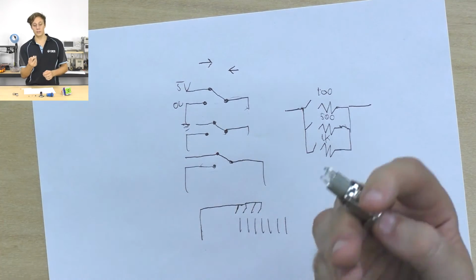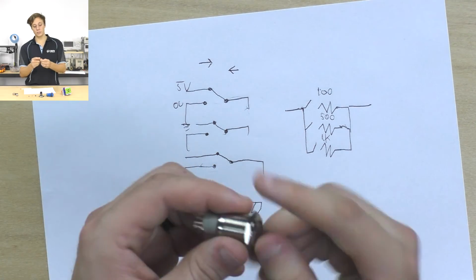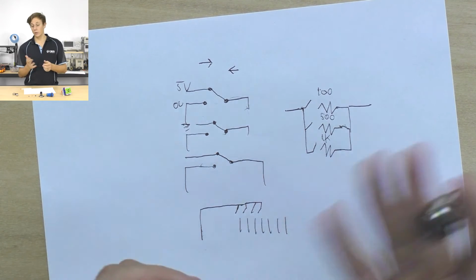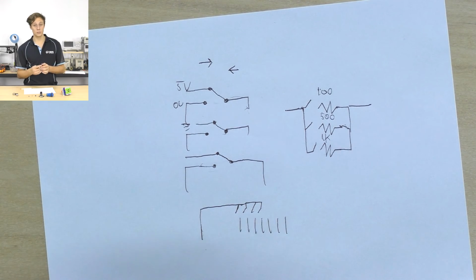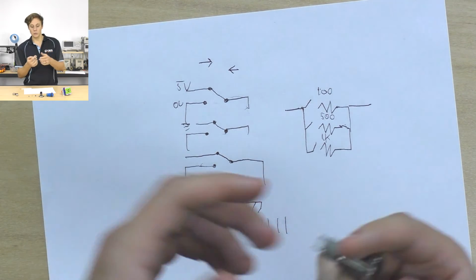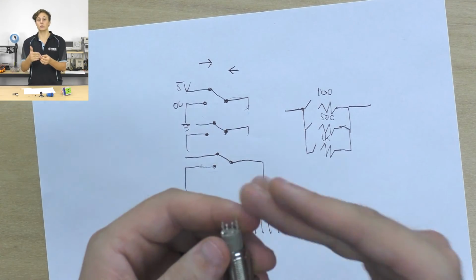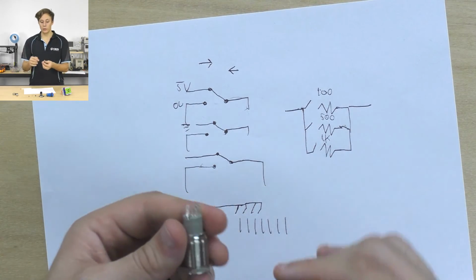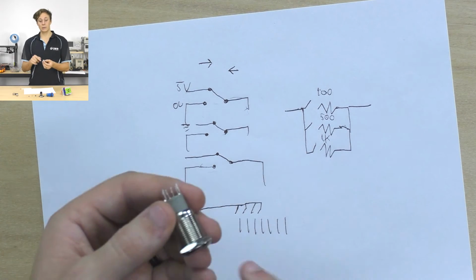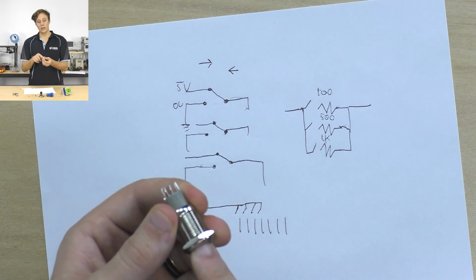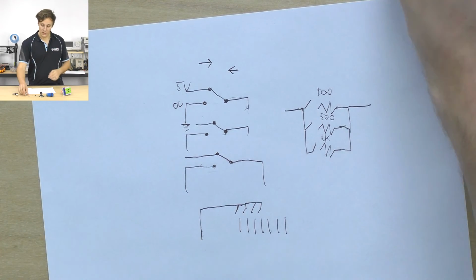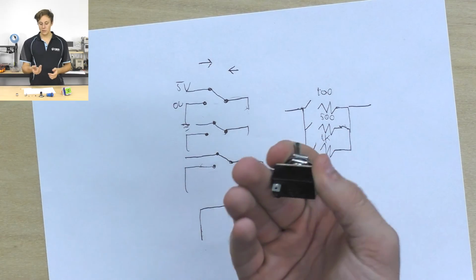So you could hook this up to a microcontroller, and it's a momentary switch. I can feel that the switch is going to the same point, and on the data sheet it says that it's a momentary switch, and you can tell that you could use this for a whole bunch of different applications. You could control a microcontroller input and then have the microcontroller control the LED, or you could hook the LED directly up to the switch contact. So when you're holding it in, the LED turns on, or when you release, it turns off, things like that.